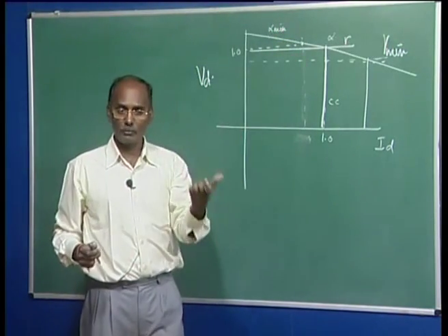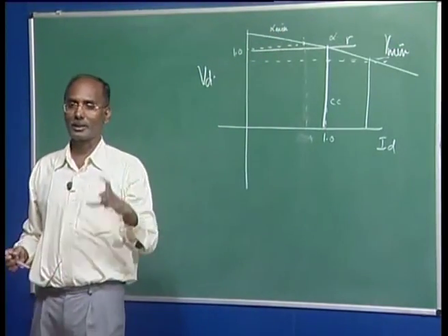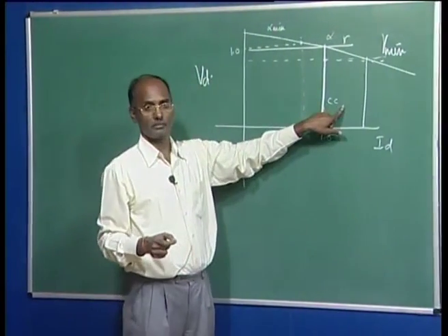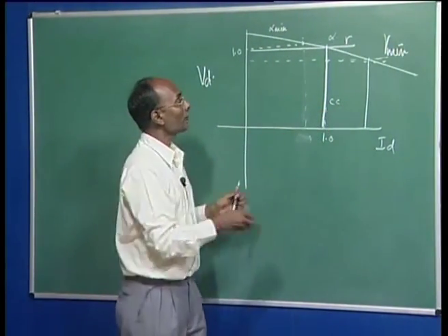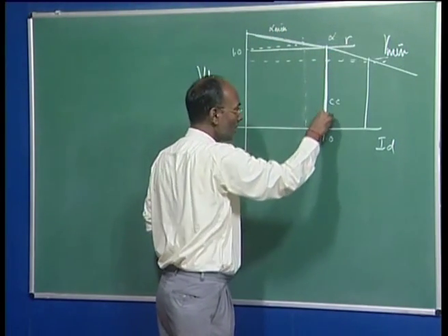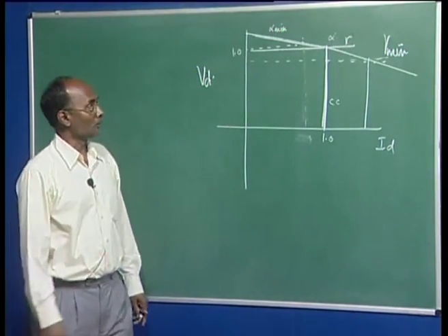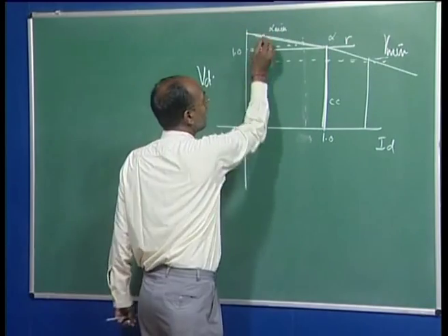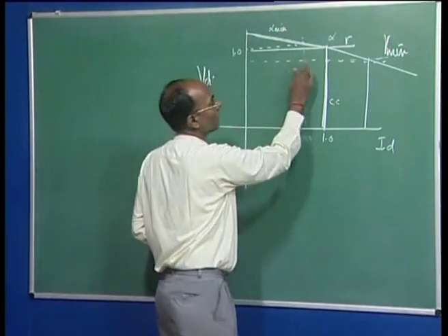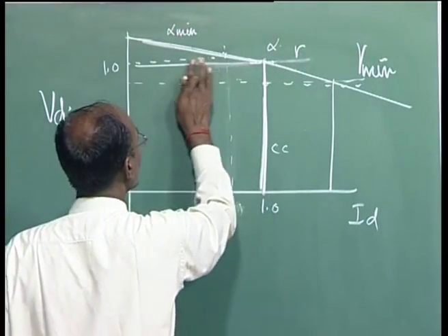So what we require is that the rectifier should control the current of the link, and that is called the constant current controller. So you see the rectifier control characteristic here. Now there is even the possibility, even though this characteristic has gone down here, that we can take any characteristic of this gamma.